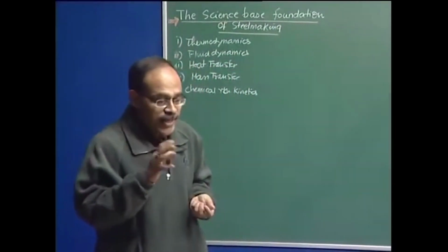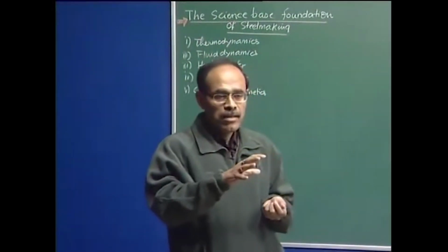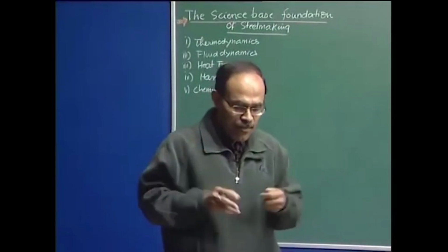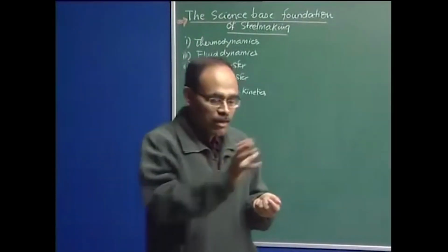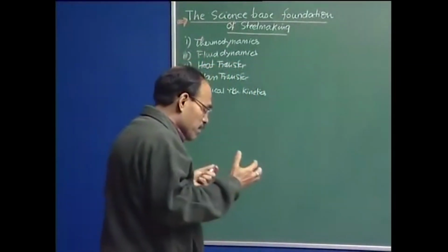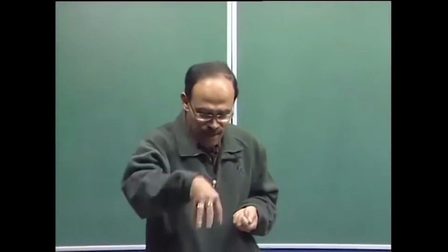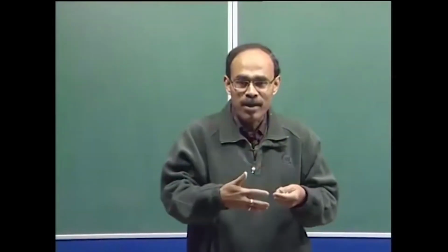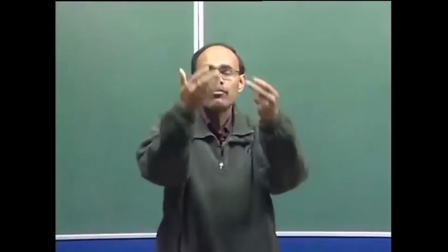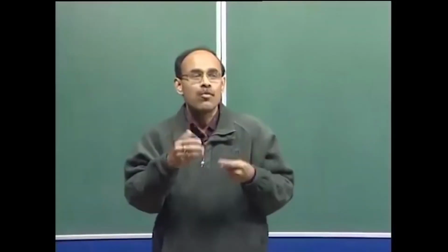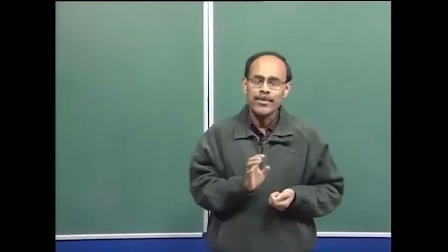Now, intensity of flow is very important for us, and the intensity of flow depends on the system geometry. It depends on the power, which is stirring power, we say, which is being fed into the reactor, and the level of intensity will eventually determine the outcome. For example, if you have added an alloying addition and you want the alloying addition to melt and dissolve in the bath, you invariably will conclude that greater is the stirring rate in the system, greater is the movement of the fluid, more will be the rate, or faster will be the rate of melting and dissolution. So, there is no ambiguity as far as the relevance of fluid dynamics in steel making.